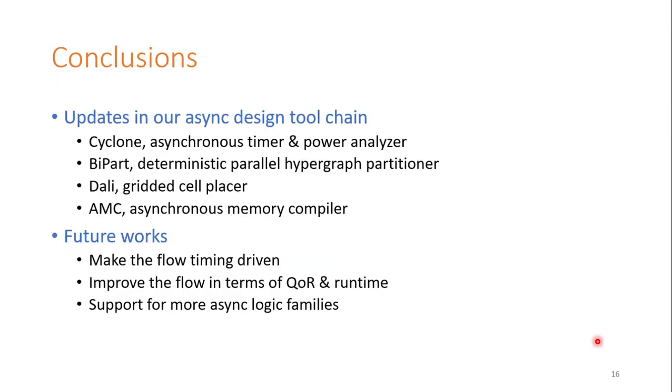To conclude, I've gone through updates in our asynchronous design toolchain, specifically for Cyclone, an asynchronous timer and power analyzer, for ByPart, a deterministic parallel hypergraph partitioner, Dali, a gridded cell placer, and for AMC, an asynchronous memory compiler. In the future, we plan to make the flow timing driven, improve the flow in terms of quality of results and runtime, and support more asynchronous logic families.